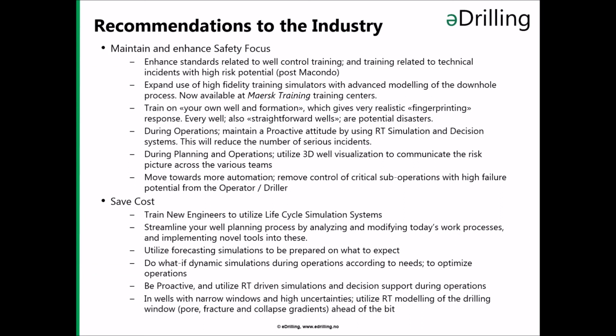Also, to save cost, you should be proactive and utilize the tools which are relevant for enhancing and increasing the way to proactive. And in wells with narrow windows and high uncertainties, the industry should also utilize the possibility to do real-time modeling and updates of the drilling window, meaning the pore, the fracture and the collapse gradients ahead of the bit. This will both save costs and enhance safety.